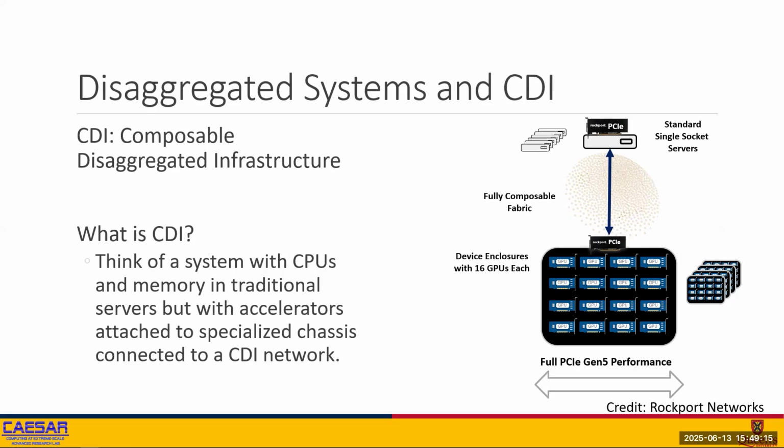Okay, so you've got a system with traditional CPU and memory servers, but you've taken all your accelerators out of them. So these servers could be just half decent CPU type things that are sitting over here that could be like 1U, little tiny blades, anywhere to just a traditional server that you didn't fill up with a whole bunch of GPUs, right? And you move these all over into these chassis, which for physical purposes are just big boxes you plug a whole bunch of PCIe cards in. But for the purposes of these disaggregation networks, all we're really doing is encapsulating PCIe over networks, tying things together with intelligent, transparent memory translation in terms of the PCIe domains, such that you can tie all this stuff together and just looks like it's all connected.